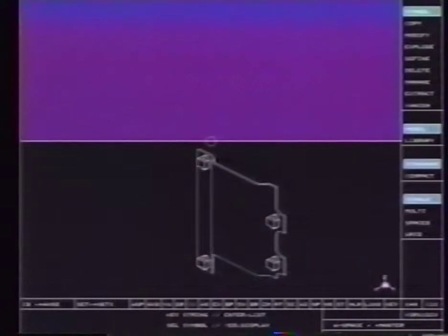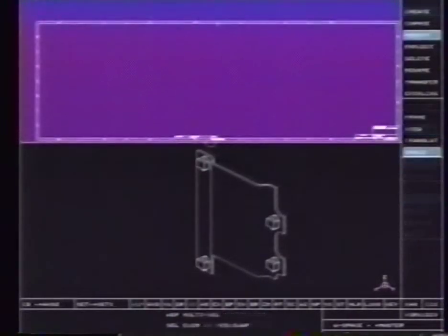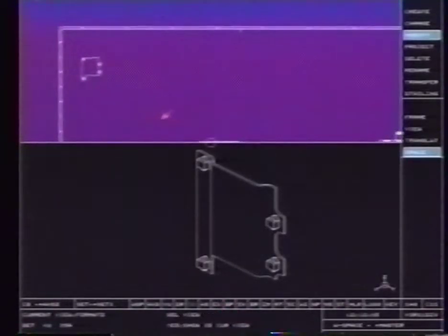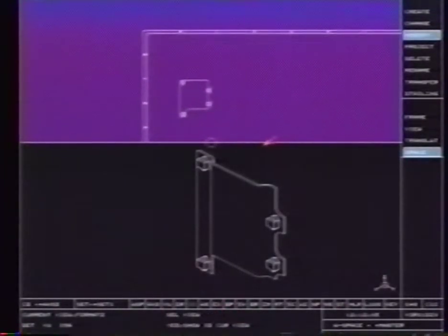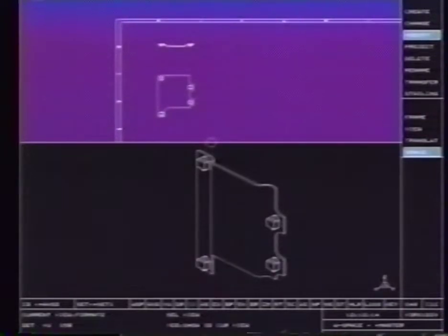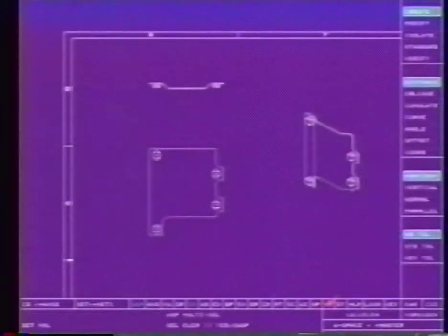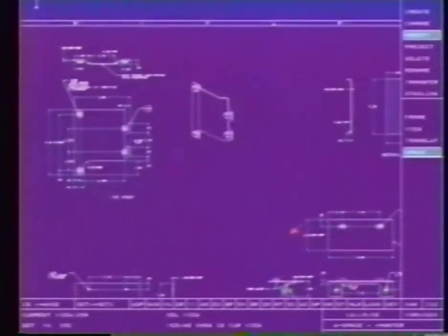When the design is finished, the engineer can begin to create the dimension drawings to be used in the shop. Formats are placed on the Draw Space section of the screen, and auxiliary views are created which are actually just different perspectives of the 3D workspace. Filters are used so that only the desired part or combination of parts are seen in each view. After the views are created, dimensions and text can be added to complete the drawing. Finally, a print of the drawing rolls off an electrostatic plotter.